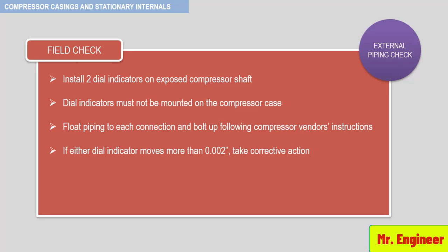Just keep in mind that excessive casing forces from process piping and foundations are one of the major sources of misalignment. So my advice to you, talk with your maintenance team and stay informed and updated of any work on process piping systems or foundation, and prepare guidelines to control and monitor this work.